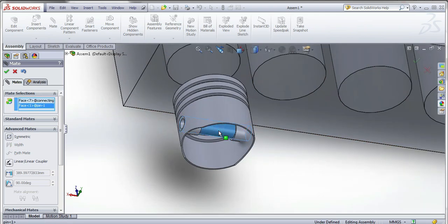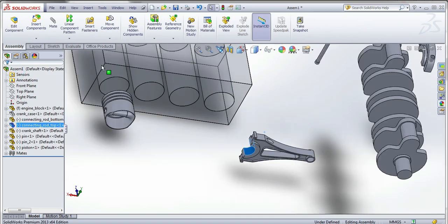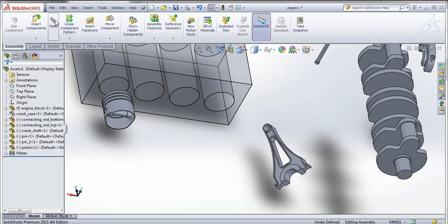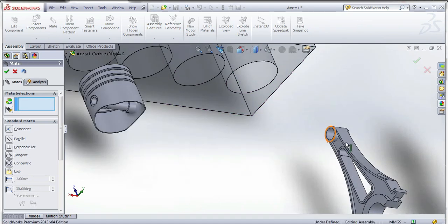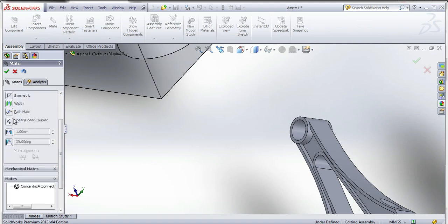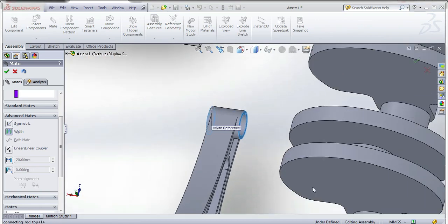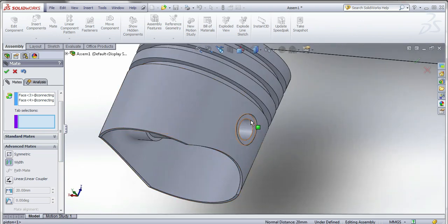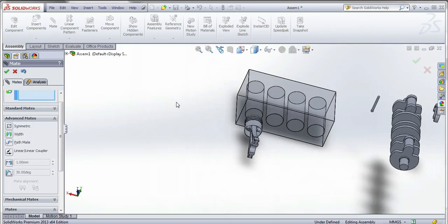And select connecting rod. So to rotate. Okay. This also same, the width command, advanced mate. The connecting rod is locating on the center one. The two side surfaces. Connecting rod center is identified. And the next one, the piston, to piston center surface automatically mapped centrally.